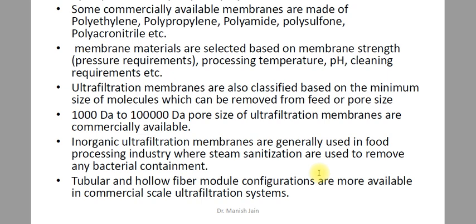And if you are using it for concentrating fruit juice, or clarifying fruit juice, meaning removing the different types of microparticles present in the juice by using ultrafiltration, then you have to be conscious that bacteria should not start to grow at the surface of the membrane. For that you have to use steam sanitization at different time intervals.